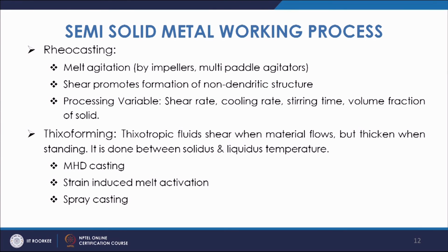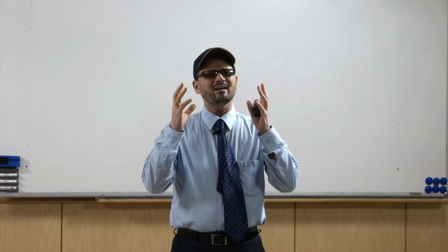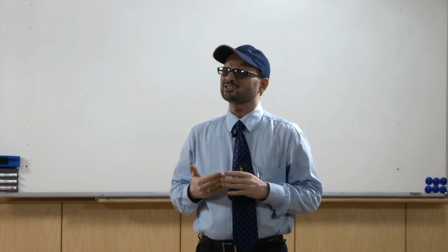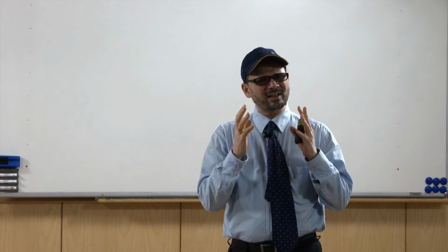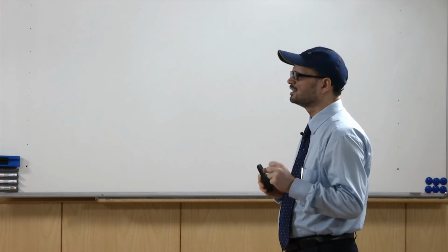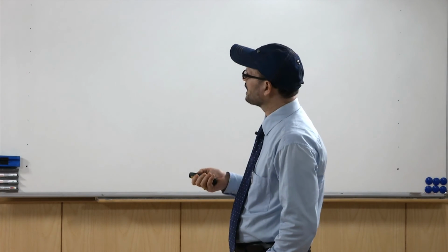So, what is Rheo casting basically? In this semi solid metal working process, the aim is to avoid the dendritic type of structure, and you try to get favorably equiaxed globular structures. Now, what is that process which induces all that? So, the Rheo casting is there.